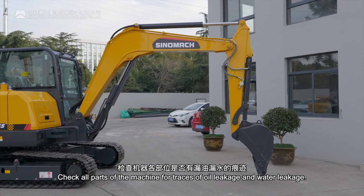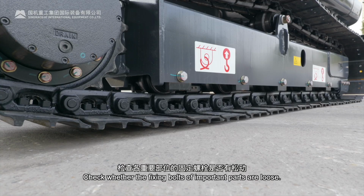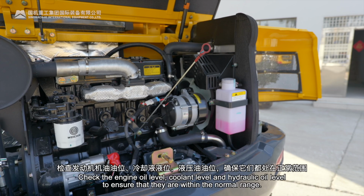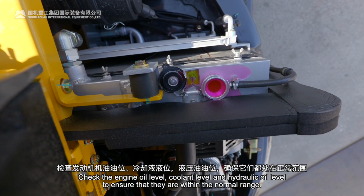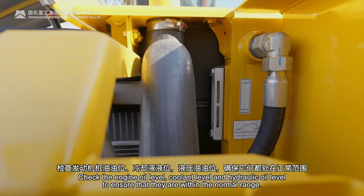Inspection before starting. Check all parts of the machine for traces of oil leakage and water leakage. Check whether the fixing bolts of important parts are loose. Check the engine oil level, coolant level, and hydraulic oil level to ensure that they are within the normal range.